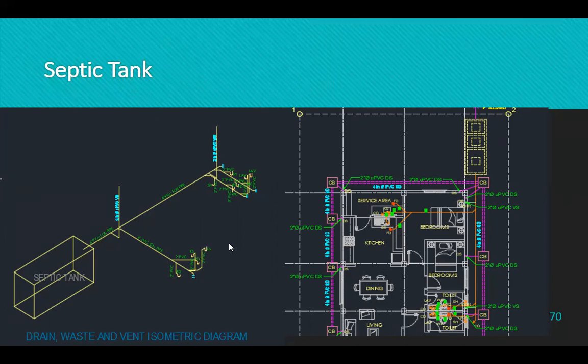Isometric, mag-isometric kayo. Kaya check niyo yung mga reference kung paano mag-isometric. Huwag niyong gayahin yung floor plan, tinatabingin lang. Diba? Mali yun. Kasi pag lagay mo na yung water closet mo, laboratory mo sa floor nakalagay, yung tubong closet mo sa taas.